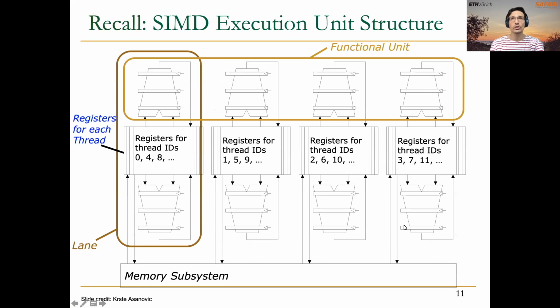And when we talk about a functional unit, we mean all execution units that are available to execute specific instructions in the SIMD hardware or inside the GPU core as well. We may have several of these functional units, same as we have just seen in the core of the H100 GPU. Different functional units may have different purposes. Here we can see a functional unit, and we also see a different one here.